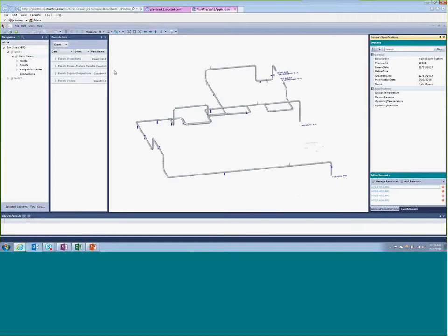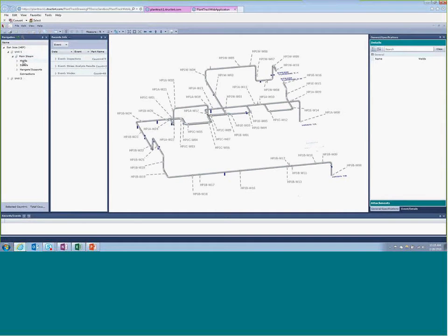So one of the things I'm going to start with is risk-based prioritization. When you look at a particular system that has hundreds of welds, in some cases 300 plus welds, where do you start? Where do you start to prioritize where to look, to get ahead of any damage that will occur? These systems are designed as best they can, but as I'm sure most of you are well aware, damage does occur, including common industry issues, et cetera.